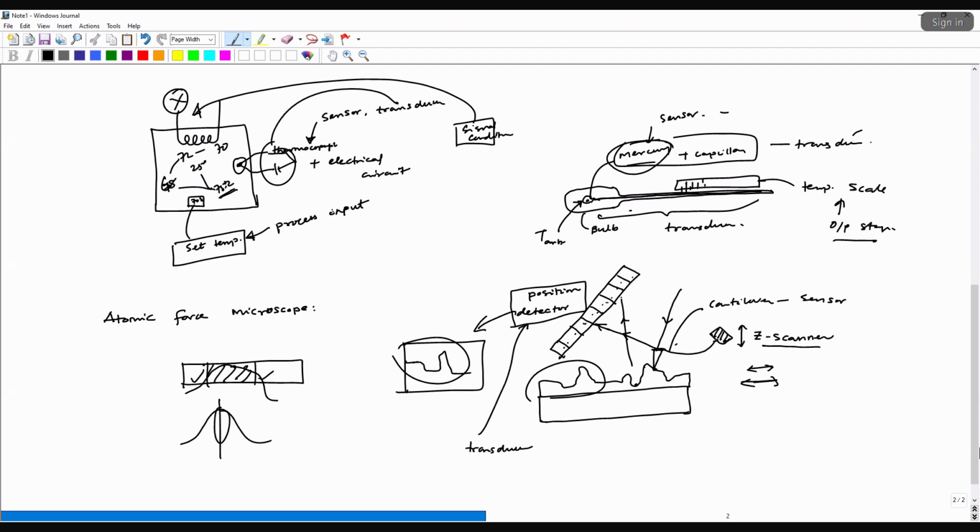The purpose of signal conditioning would be to ensure that the position detectors are appropriately identified. You chop the signal falling on these side detectors and only consider the maximum intensity. So if there are three detectors, you say the light is falling on the second detector, not on 1 and 3.